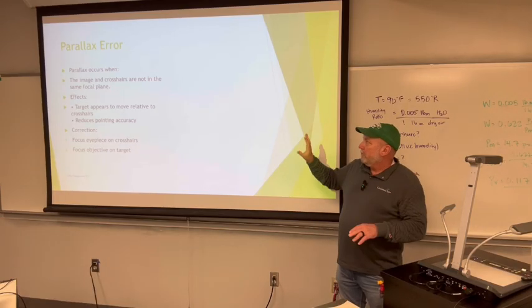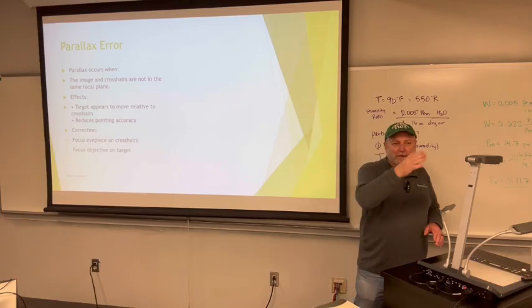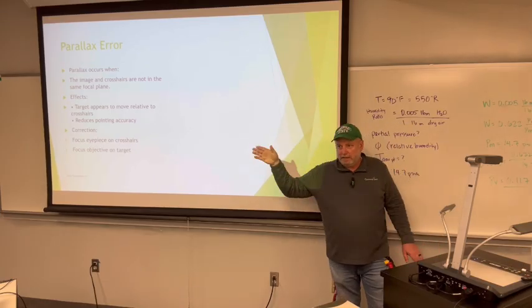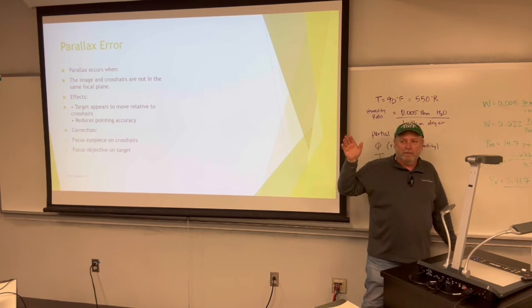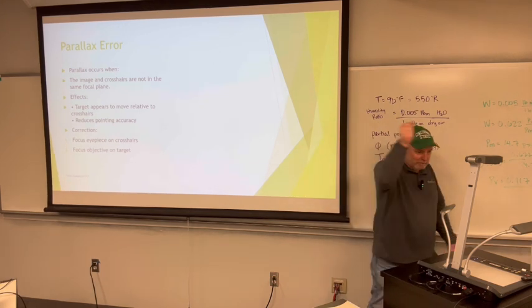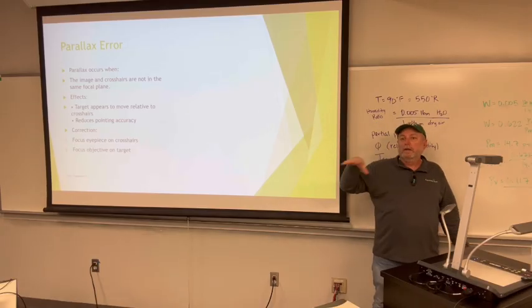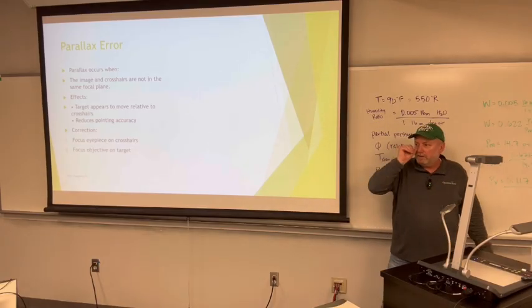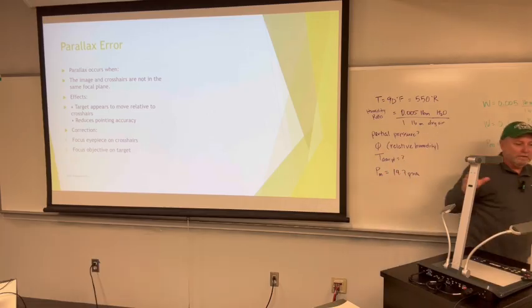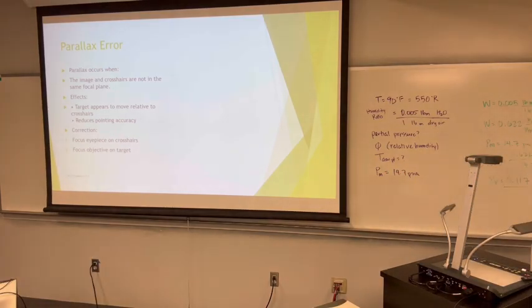So with your robotic total station, if you're running around doing topo, collecting data, or doing stakeout, if you've got an auto lock prism and you're just walking and it's following you, parallax doesn't really matter. But it does matter every place else. It's still a thing. Be aware of it. Do your best to avoid it. Any questions?